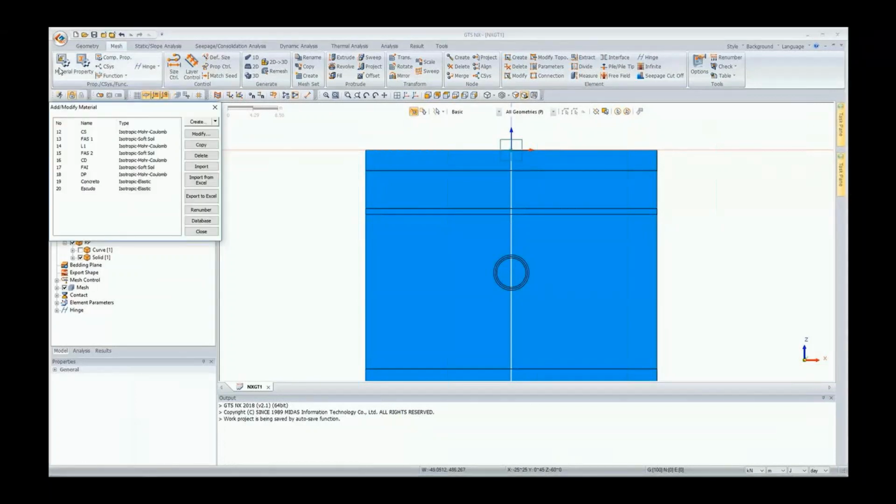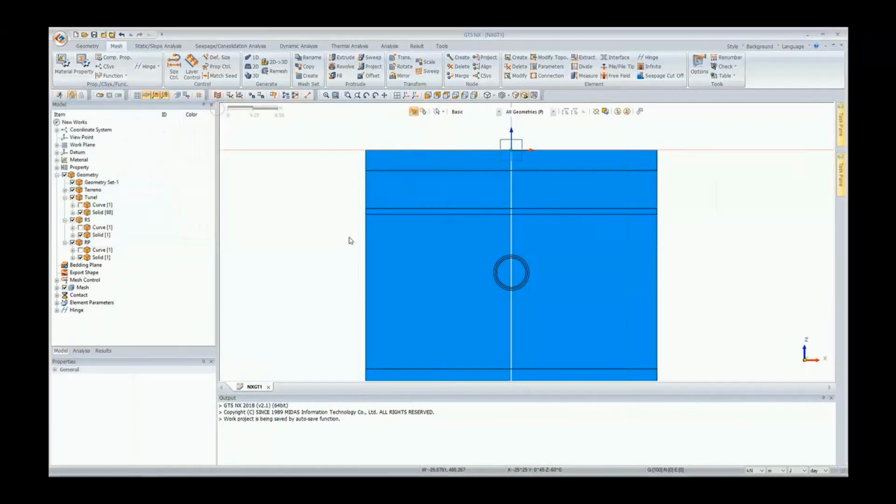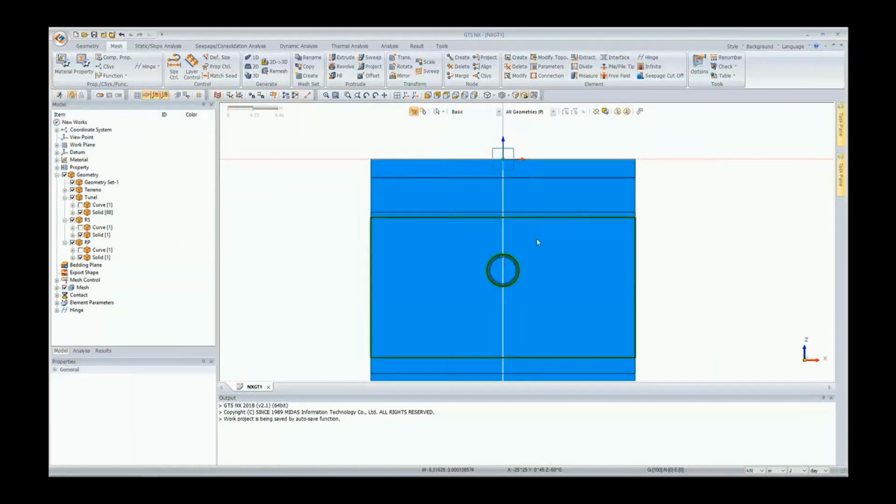And this imported the materials, as we see here, which constitutive model is assigned to each of the soil layers. So we see we have these four with Mohr-Coulomb for the more rigid terrains, and then for the clays we're using soft soil, as well as the concrete and the shield for elastic. So now we can actually go into the meshing.